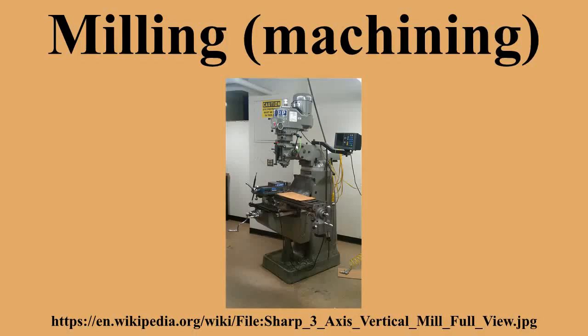One other subtle difference between these two tool holders is the thread used to hold the pull stud. CAT tooling is all imperial thread and BT tooling is all metric thread. Note that this affects the pull stud only, it does not affect the tool that they can hold. Both types of tooling are sold to accept both imperial and metric size tools.